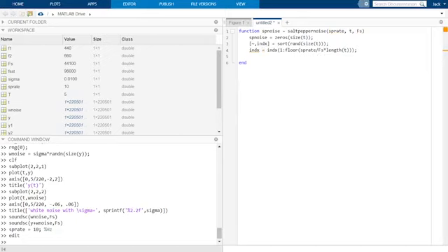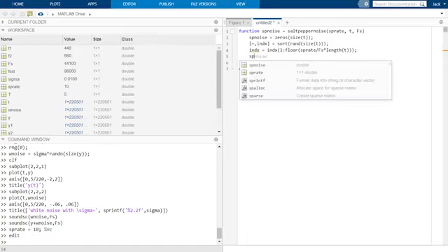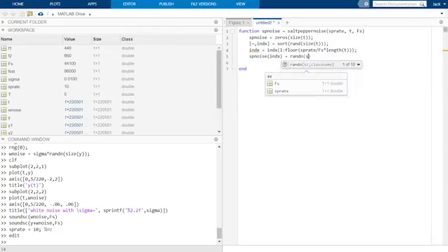So that we get indices randomly distributed over the course of the signal with an average density of 10 locations per second of sound. For each of these indices, we will define the value in SP noise to be a normally distributed random number. This process will create an average of 10 crackles per second, each with random magnitude and randomly distributed over the course of the sound.